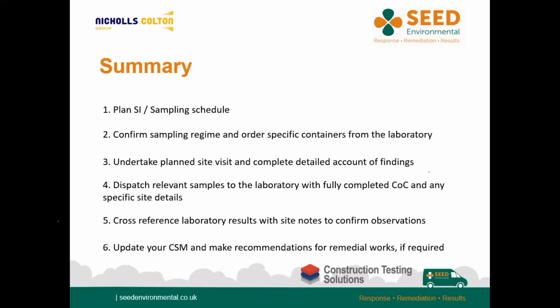You will need to consider: will hand auger or spade be sufficient, or does a drill rig need to be mobilised to site? If you are unfamiliar with the contaminants you expect to encounter at a given site, speak to the laboratory in advance, as you may need specific containers or preservatives which need to be issued before you attend, to ensure your samples are preserved correctly and do not deviate. Whilst on site, maintain a dynamic view of the site when collecting your samples. Consider each set of infield results with respect to what you're observing and make detailed notes on the sample geology, water strikes, and visual and olfactory evidence of contaminant impact.